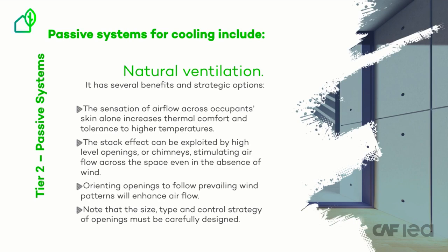Firstly, the sensation of airflow across occupant skin alone increases thermal comfort and tolerance to higher temperatures. Secondly, the stack effect can be exploited by high-level openings or chimneys, stimulating airflow across the space, even in the absence of wind. Thirdly, orienting openings to follow prevailing wind patterns will enhance the airflow. And lastly, note that the size, type, and control strategy of openings must be very carefully designed.